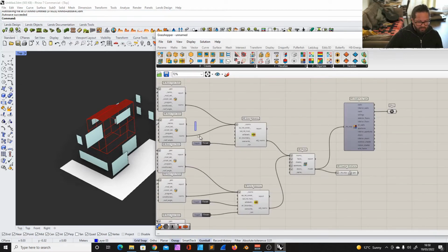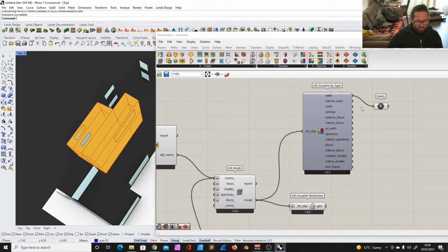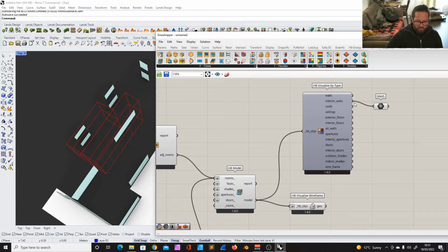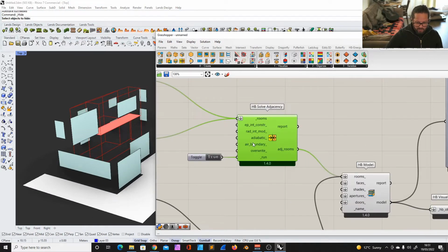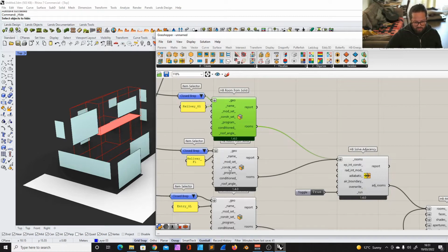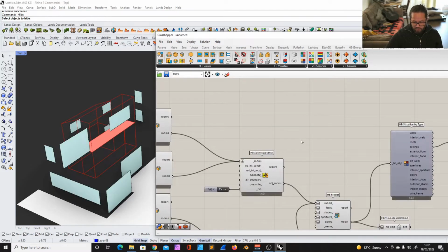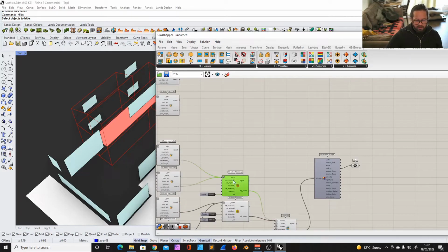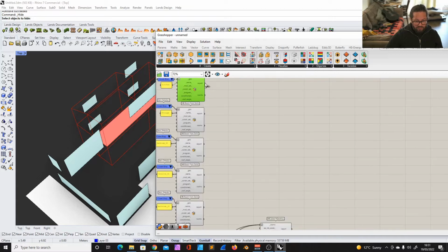So you really need to think your adjacencies through in order to build it correctly. So I hope it's more clear. We have outer walls, we have no interior walls because this is all open, but we have roofs and ceilings, and the ceiling only on this side because here we don't have an air boundary. The hallway on the ground level and the hallway on the first floor are divided by this floor. Now I can copy this again, and I run the adjacency between all these other rooms here on the ground level.